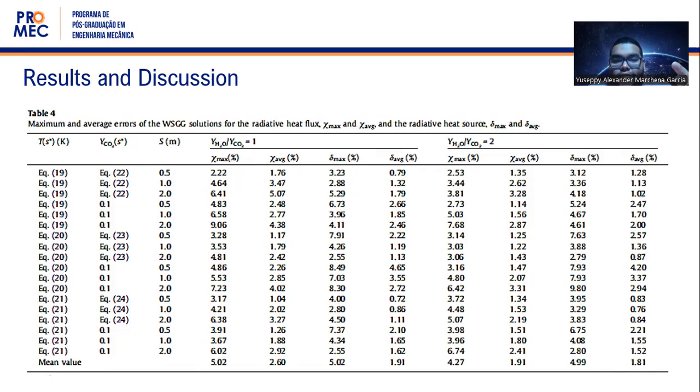In both cases, our WSGG method is significantly accurate compared with the L by L integration method. Additional cases with constant concentration of carbon dioxide present errors of similar magnitudes, which highlights the difficulty of correlating the model errors with a single physical parameter.